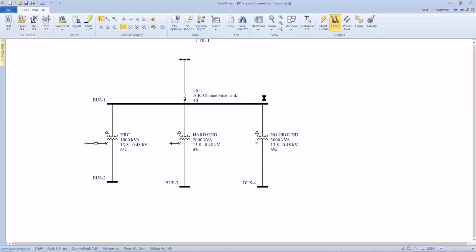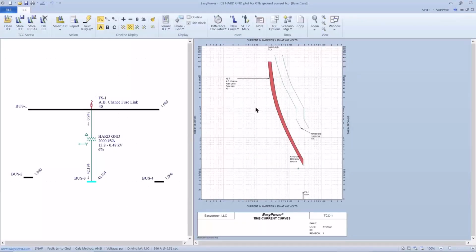That's just what we were seeing. And so if I have primary protection, I need to make sure it protects me from currents that potentially exceed this shifted curve. Now, if I have secondary protection, I can disregard that curve and make sure that I'm not exceeding the 100% damage curve or the frequent fault curve.